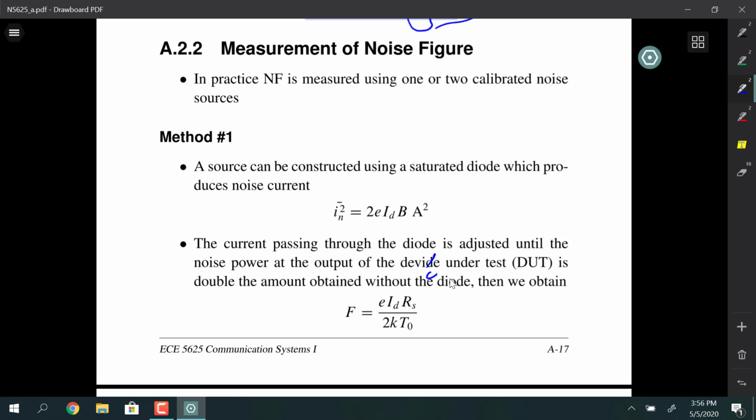And I wasn't an expert at building low noise amplifiers. I just followed some examples that the previous generation of the system had used and bought some kind of expensive microwave transistors and designed a PCB, and it got put inside a little tiny aluminum machined housing, and that was the preamp. And it sat remote from the rest of the electronics. It sat right at the back end of the photomultiplier tube. Kind of like my analogy to Dish Network, where you'd have a preamp right at the back of the antenna on the side of your house.